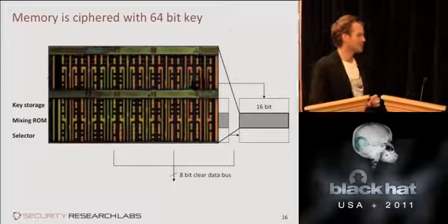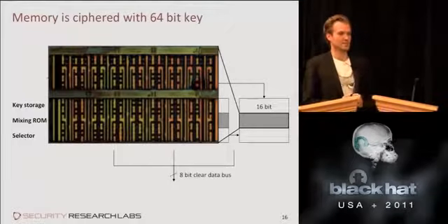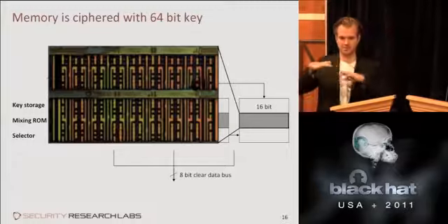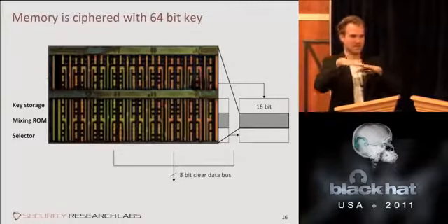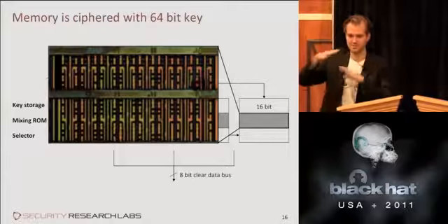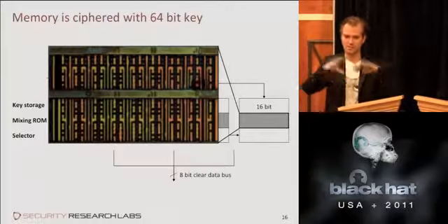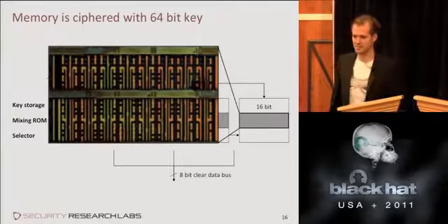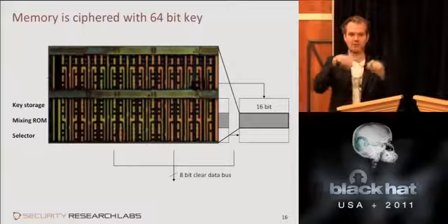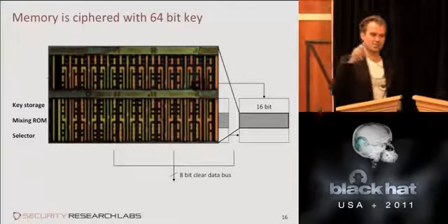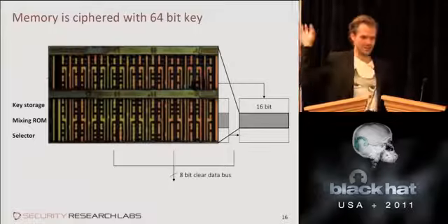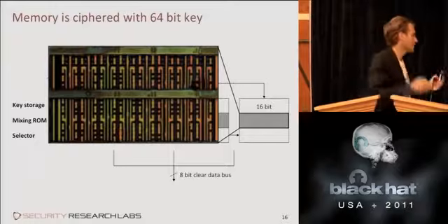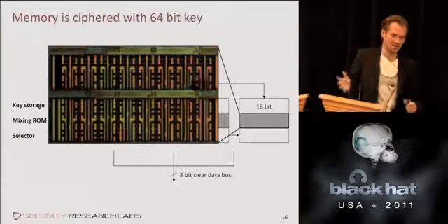We've seen other chips where the customer of the chip, who I guess gets some part of the chip remade, usually the ROM mask, so some metal layer, but nothing else of the chip, gets a little kind of Lego toolbox to play with: some area of the chip where there's gates that are not connected to each other, but the possibility of routing wires in between them. So that actually changes the algorithm in ways that you couldn't just fill in a blank after you did your analysis. Also crackable, of course, but there's some neat ideas how to diversify.